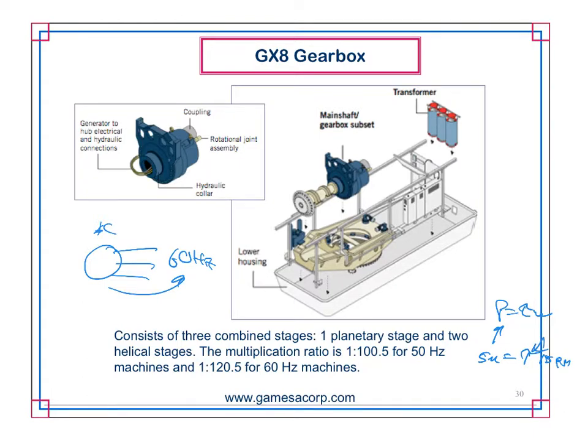If your RPM now is 3,600 RPM, you can put the same 5 megawatts out, but you need a lot less torque. So you put a gearbox in there to have the nacelle or the hub running at 15 RPM, but the generators themselves are running close to 3,600 RPM or 1,800 RPM. So you can make them far, far smaller in size.